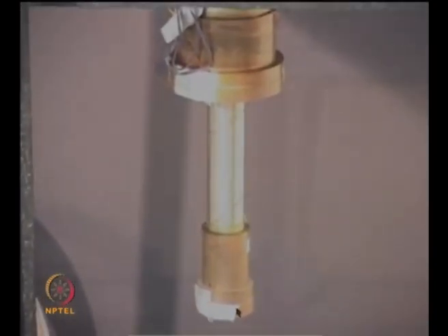So, I get a lowest temperature of the order of 8 to 10 Kelvin at this point, which is the second stage, and I get a first stage temperature of around 30 to 35 Kelvin at this point. This houses the two-stage displacer, driven by the motor, or it can possibly get driven by itself if you have a pressure drop across the displacer, and this is called a free displacer in that case. The displacer will go up and down with the frequency that you maintain, 1 hertz or 2 hertz, and the displacer also houses the regenerator.